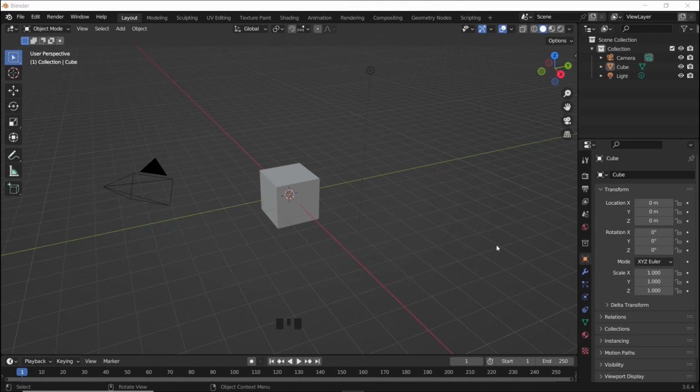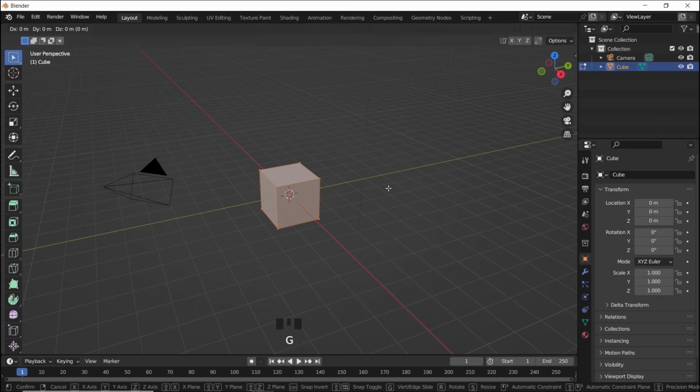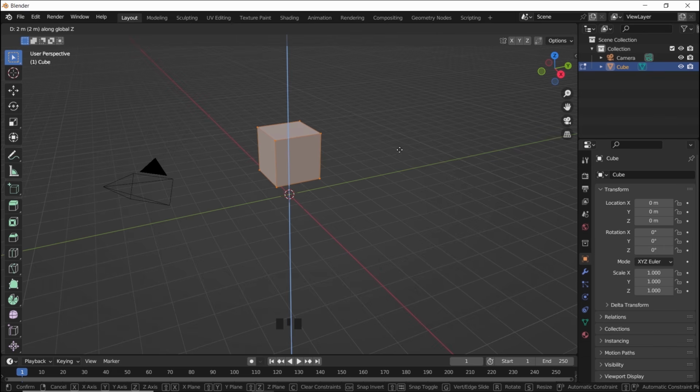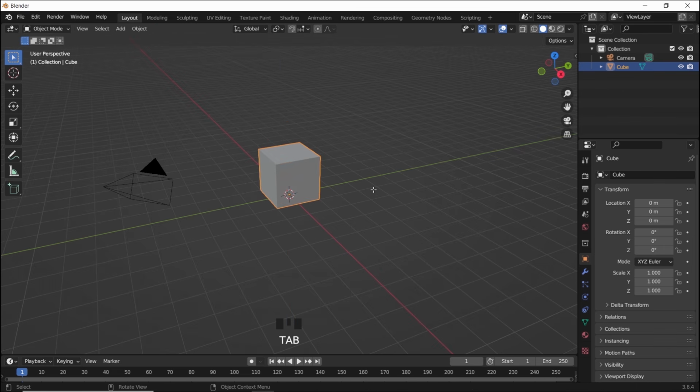Now, as most of you know, I am an advocate of the default cube right to survive, so select it, hit Tab for edit mode, and move it up while holding Control to level the bottom of the cube with the grid. This way we can scale from the floor level.